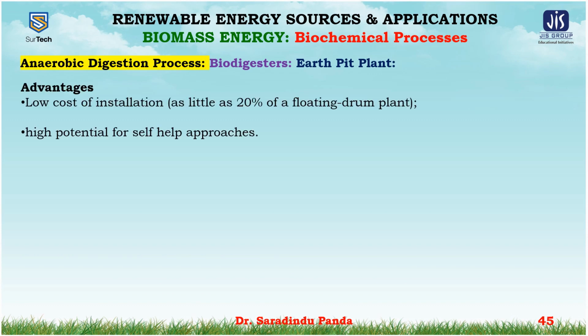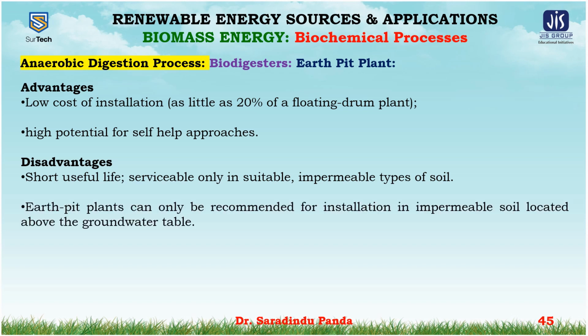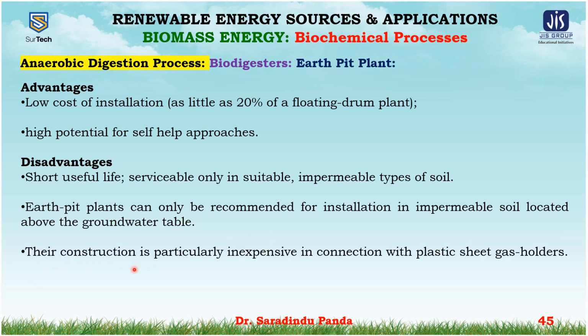The advantages of the earth pit plant are the low cost of installation and high potential for self-help approaches. Some disadvantages are the short useful life and that it is serviceable only in suitable impermeable types of soil. Earth pit plants can only be recommended for installation in impermeable soil located above the groundwater table. Their construction is particularly expensive in connection with the plastic sheet gas holder.